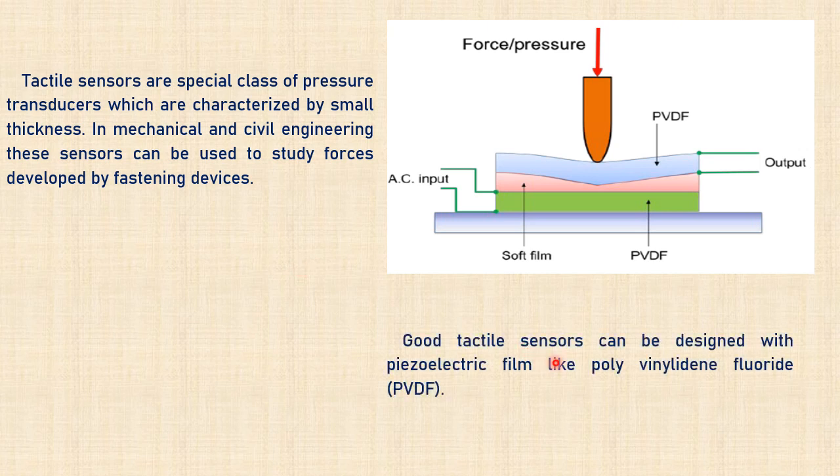Good tactile sensors can be designed with piezoelectric film like polyvinylidene fluoride. PVDF stands for polyvinylidene fluoride. So you see in this diagram, this is one polyvinylidene fluoride film, a very thin film. And then we have an intermediate layer here, the pinkish one. We call it an acoustic coupling.